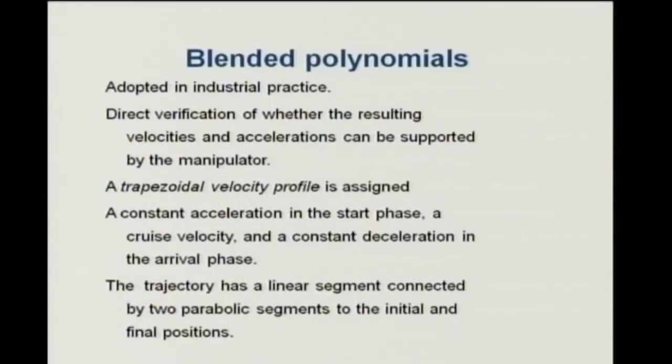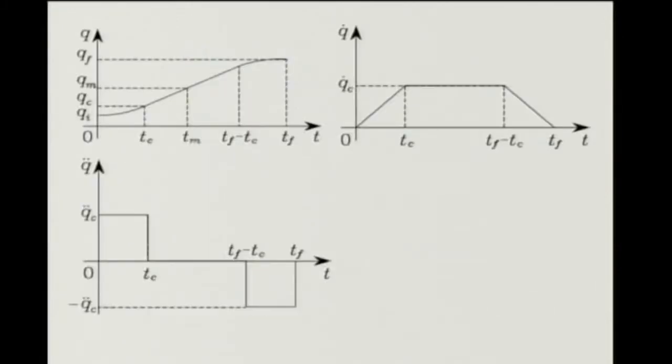So today we continue. Instead of writing a polynomial through the set of points, we decided that we will go with constant velocity for some duration, and then go with constant acceleration for some duration, then go with constant velocity and then again come down with constant acceleration.